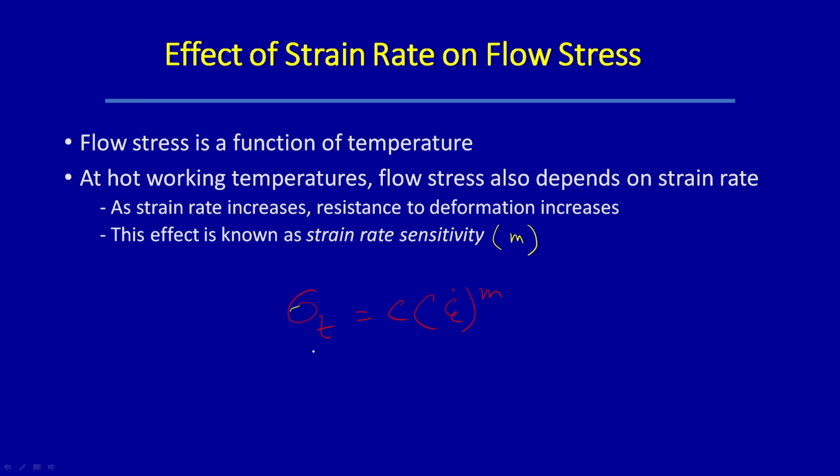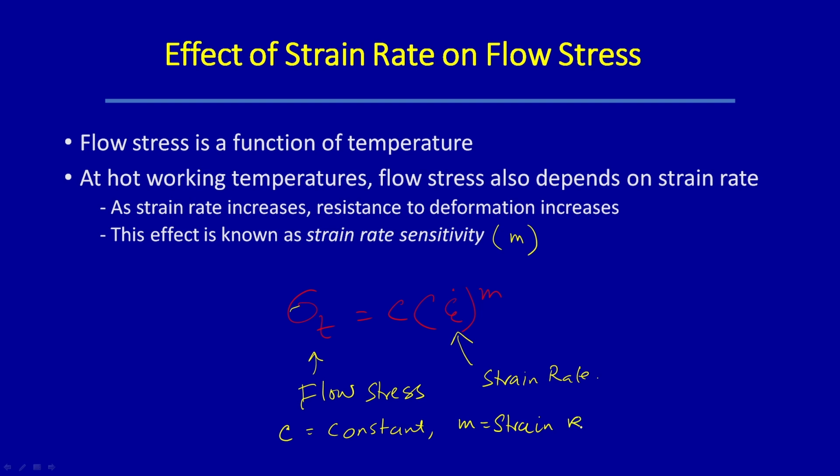So this is the flow stress, this is your strain rate, and C is a constant, and m, as I told you, is the strain rate sensitivity. Depending on the value of m, this flow stress will change, and m is a very important parameter.